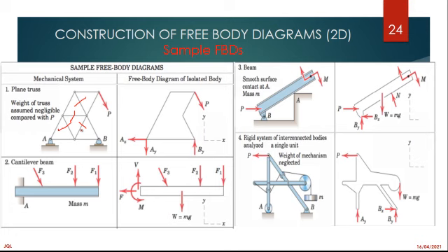I'm only looking at the external members, external forces. So I don't need anything inside here. What I'm just going to do is draw the boundary, which is this.